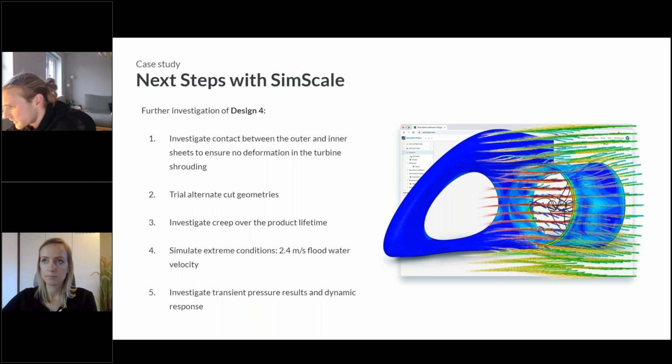Here we go, here's a technical question. We might have missed it, but how did you model the rotating zone for the turbine? Okay, now you're quizzing me on my CFD knowledge, but I believe we ran this with a multi-reference frame steady state approximation for the turbine. Is that right, Chantal? Yeah. That was a worst case scenario compared to looking at the transient analysis, which is why we took the steady state results. We compared both initially, but it was using a moving reference frame to model the blades.